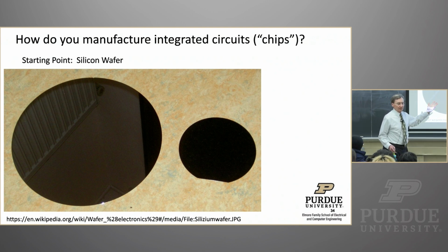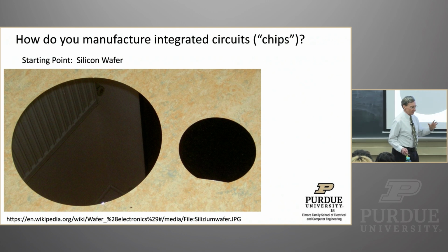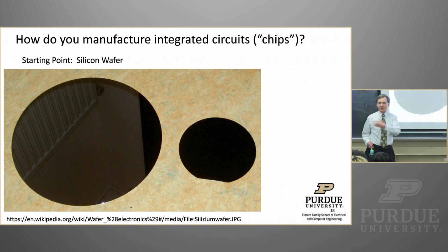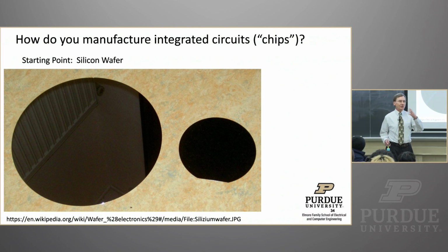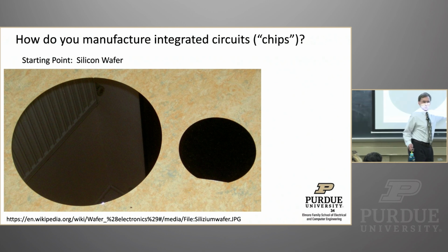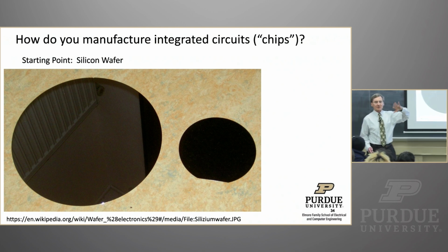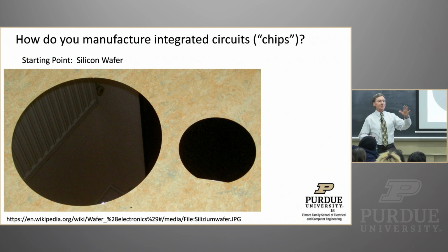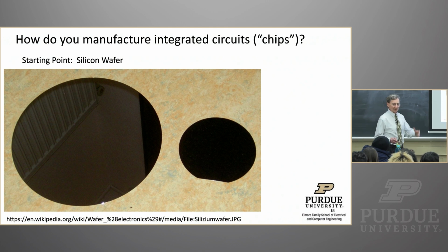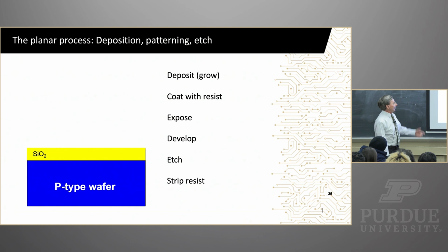We tend to talk about, the mainline, high production Taiwan silicon stuff is all 12-inch. Global Foundries does a lot of 12-inch. But there's more niche parts in the industry too that are a lot 8-inch and things like that. So there's a different variety of things. The thing to remember is that these have gotten bigger over the years. This was a much previous generation. They've gotten bigger and bigger and bigger. And so not only do we process a bunch of chips on this wafer, but the wafers themselves get bigger and bigger over time, or at least did until you got to about 12 inches, and then that's been kind of stable. So what really happens?